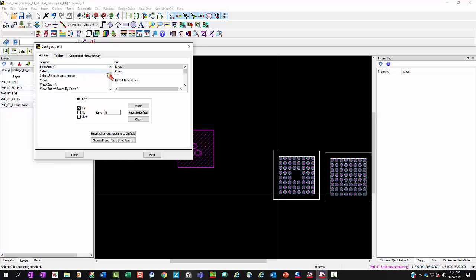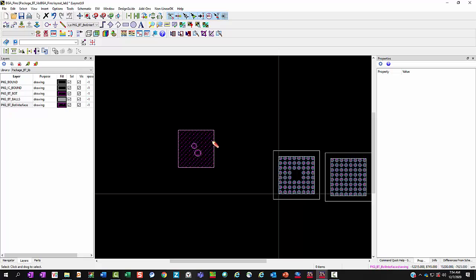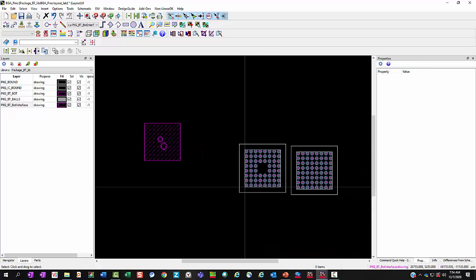But right now we're doing a hotkey, and we do insert, and this side we do a plane, and let's assign Shift plus I there, and then go assign. And then after that, if I want to insert again, I just need to press the hotkey.